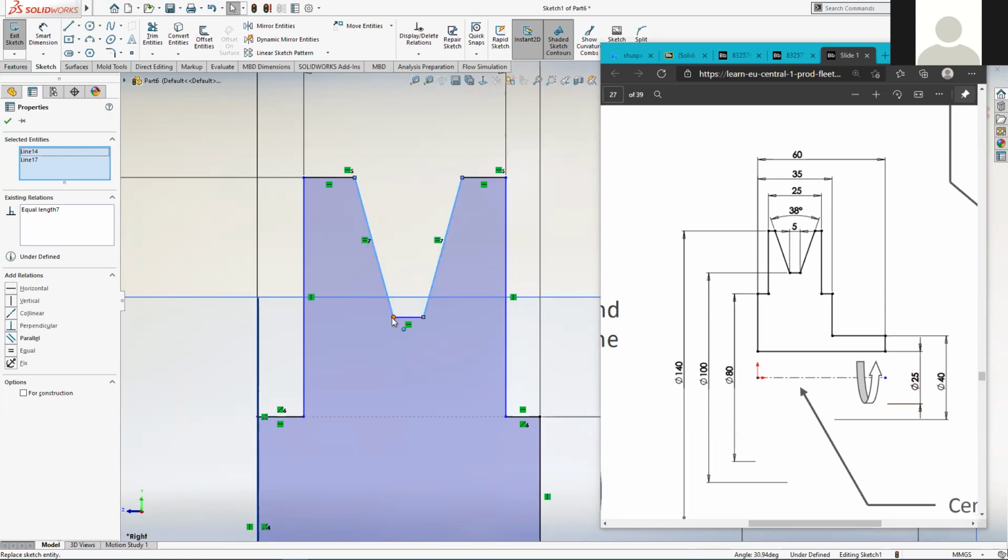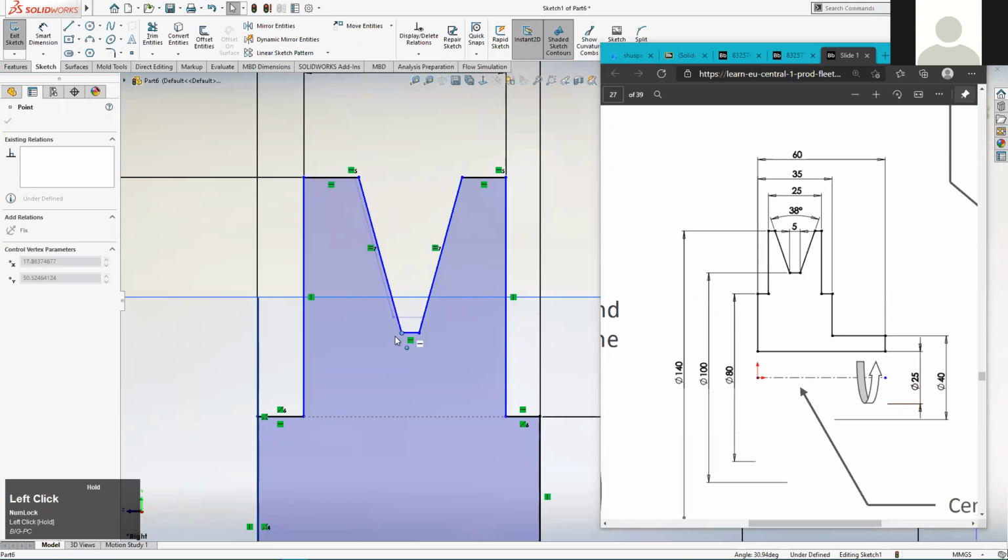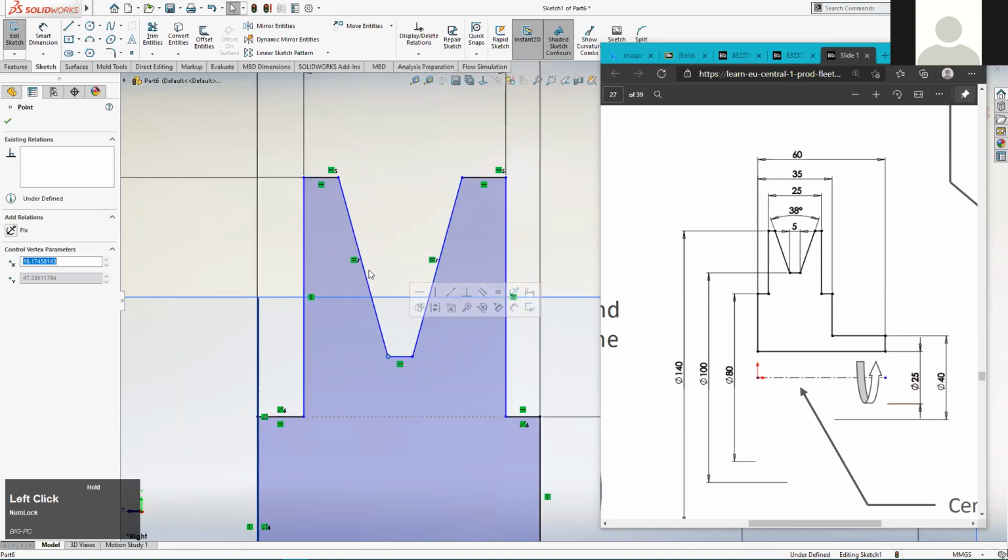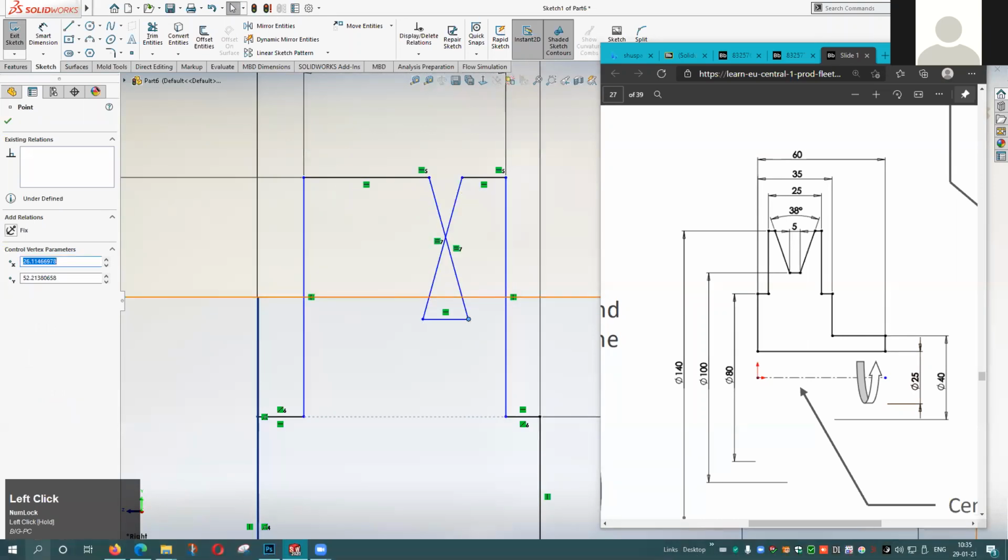So now if I try and go in and drag this around, you can see the angles of both those edges are remaining equal to each other as well as the length. Because if the lengths are set to be equal, then the angles of them must also be equal. And you can also see temporarily there when I dragged it, some of the things that can happen as you're putting your dimensions on are things such as that.